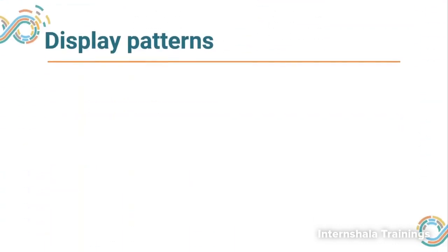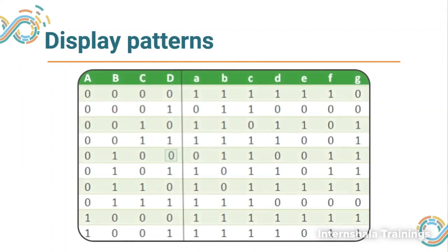So how do we generate other display patterns? Well, if you want to generate, let us say 0, then 0 can be displayed by glowing the 6 LEDs which are numbered A, B, C, D, E, F. The center LED which was G, we keep it off. And if I want to display 8, I will switch on all of them. If I want to display 1, I will switch on only B and C, and so on.